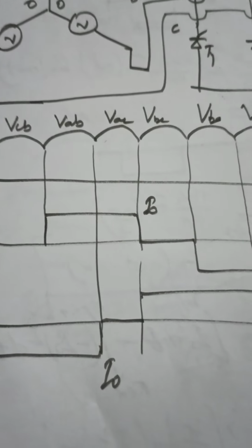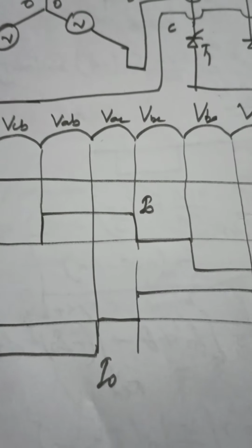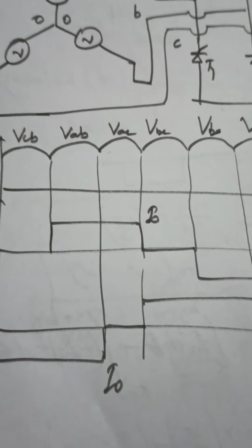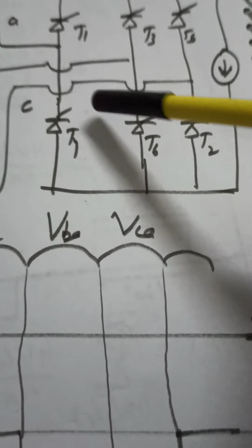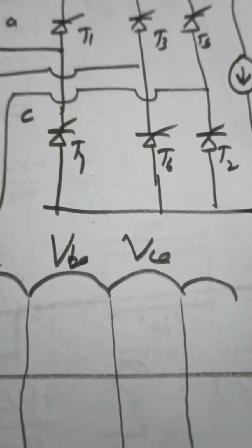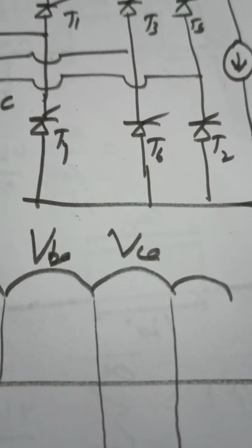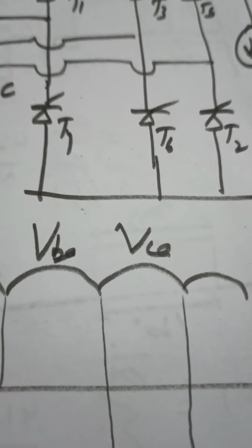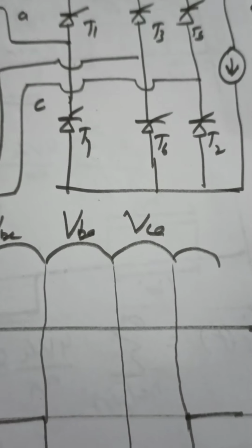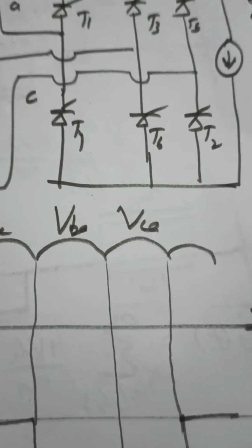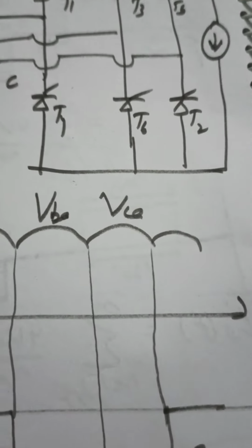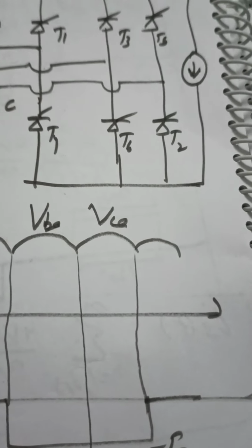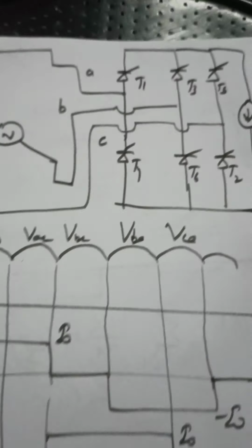now coming back to the conduction. One more very, very important thing that I want to shed light on: in the part I am discussing, I had already shown you that 5 6 will conduct, but it is not mentioned clearly at which value of alpha the conduction is going on, because alpha has to be decided. If alpha is known, then only you can trigger a thyristor. If alpha is not known, then you cannot trigger a thyristor. So in this case, have a look at this waveform.